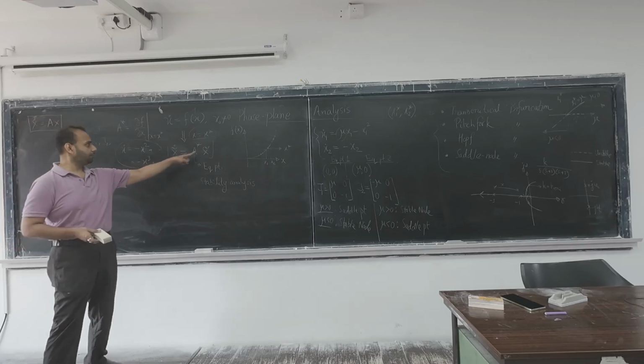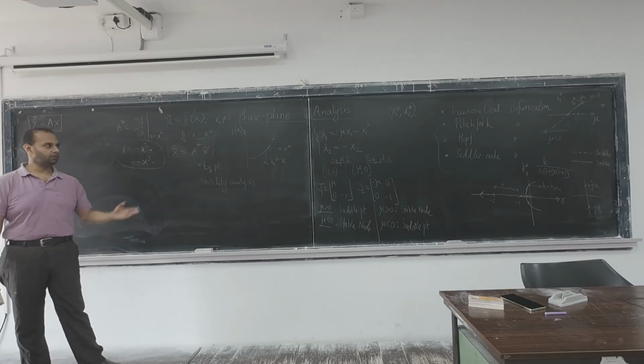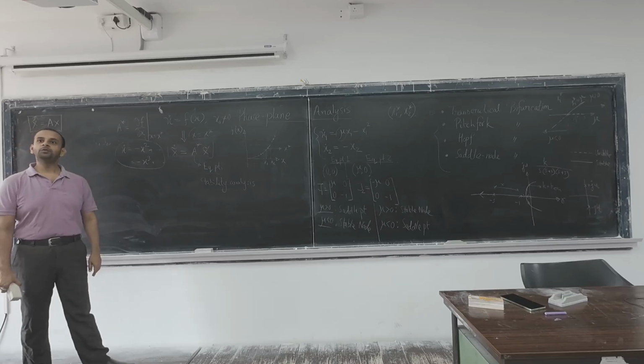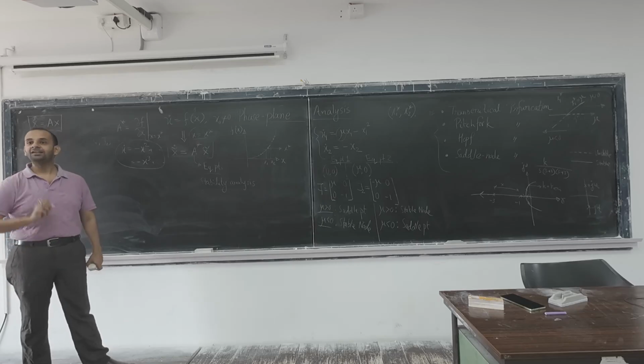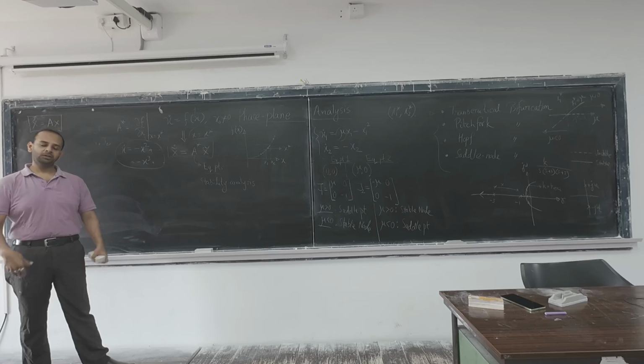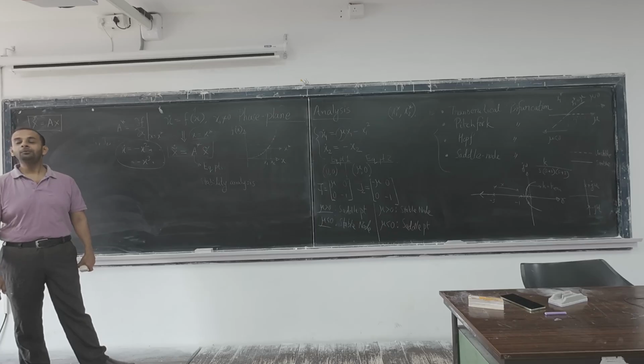Say, for example, you have x star and u star, or u tilde. Then suppose you are using an LQR controller, or even a PID. Of course, that is meant for that linearized system. Now, while the system is running, if that operating point shifts too much, then of course the accuracy of the controller will degrade. That is the reason why we learn robust control.